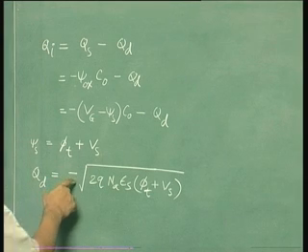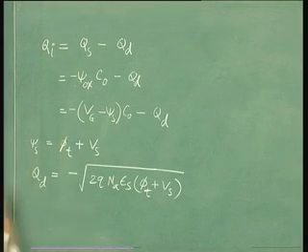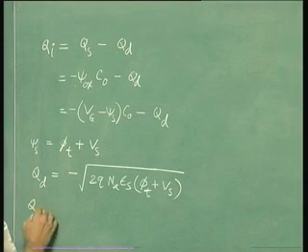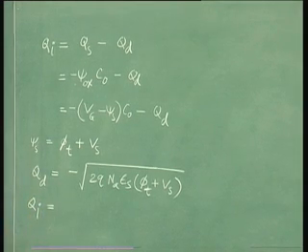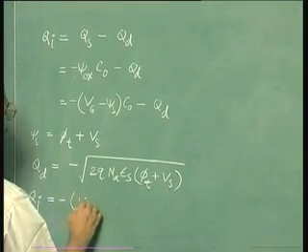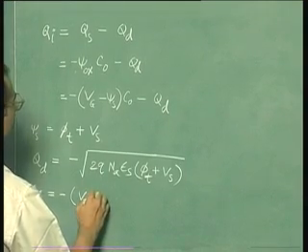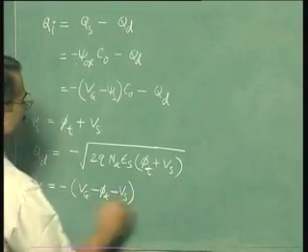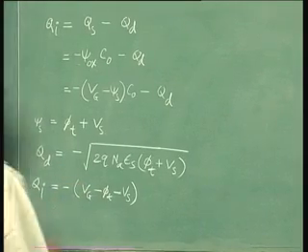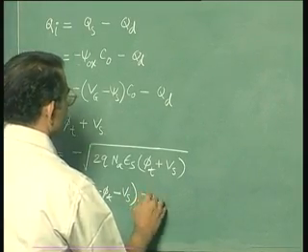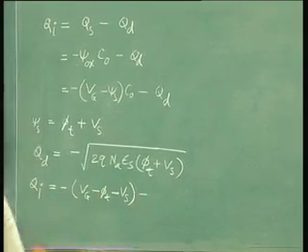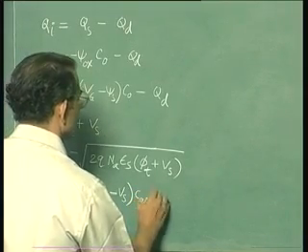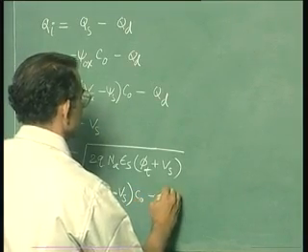So now we can substitute these two terms here, and we can get an expression for inversion charge as Qi is equal to minus Vg minus phi t minus Vs, into C naught, minus Qd.